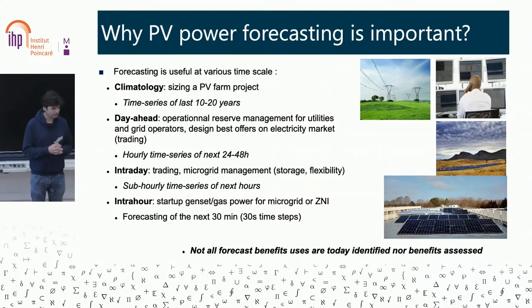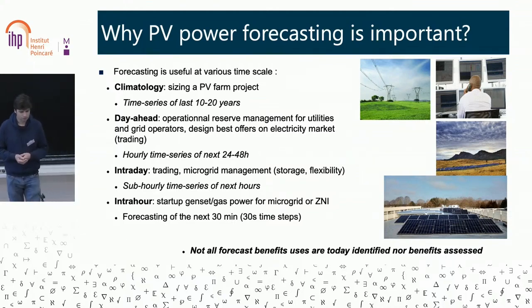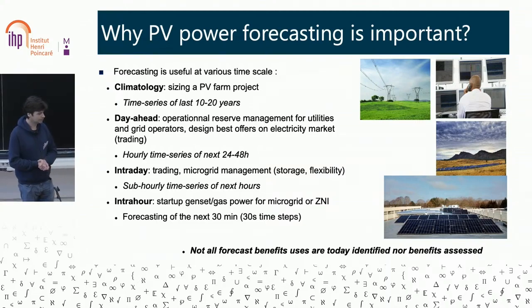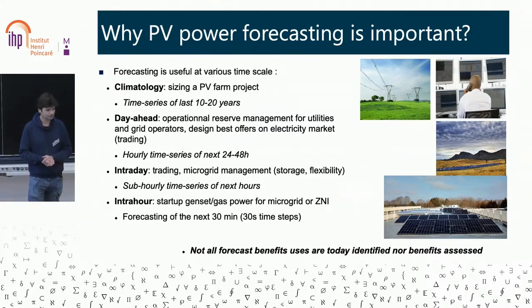Intraday forecast, there is a need for intraday forecast during the same day, also for trading, for intraday trading, but also for microgrid management, with microgrid, with storage, with battery, and how to study the flexibility, how to define the best flexibility to increase the self-consumption, for example. So in that case, this user needs sub-hourly time series of PV power during the next hour. And the last case is intra-hour.